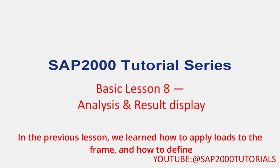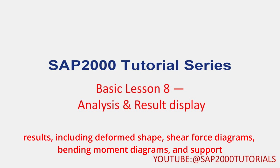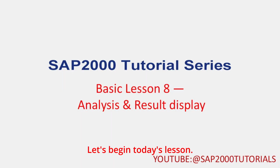In the previous lesson, we learned how to apply loads to the frame and how to define load patterns and load combinations. In this lesson, we are going to learn how to run the analysis and how to read the analysis results, including deformed shape, shear force diagrams, bending moment diagrams, and support reactions. From these results, we can understand how the support and the end release affect the behavior of the structure. Let's begin today's lesson.